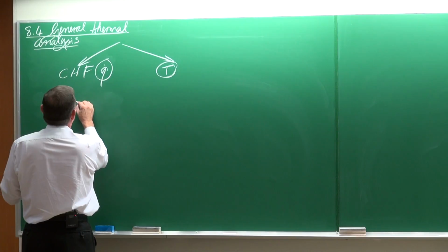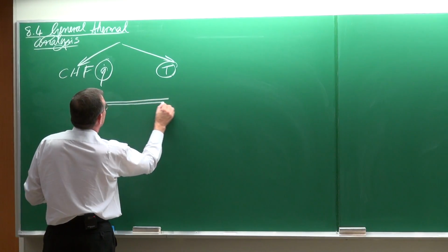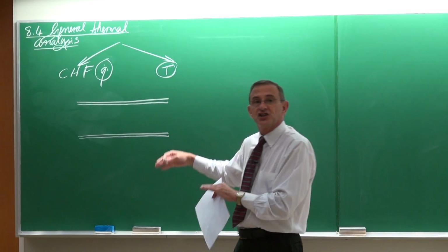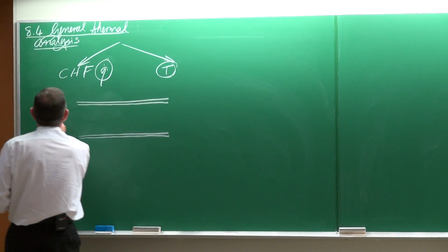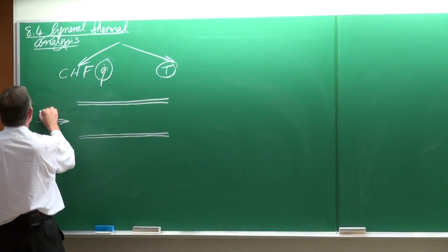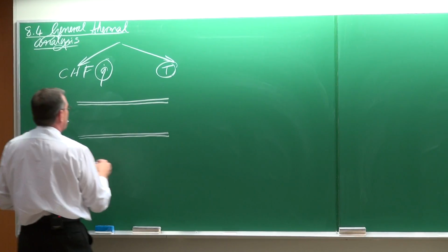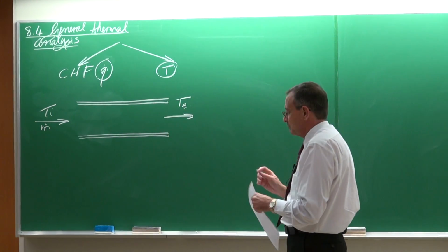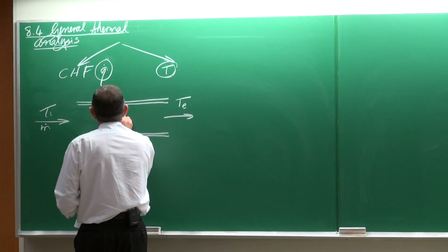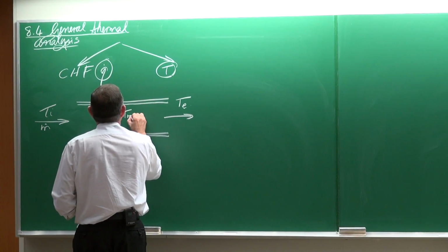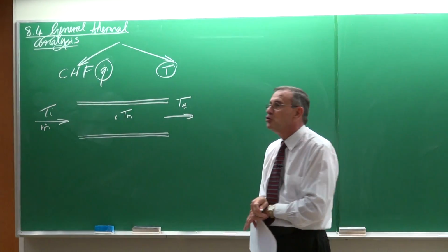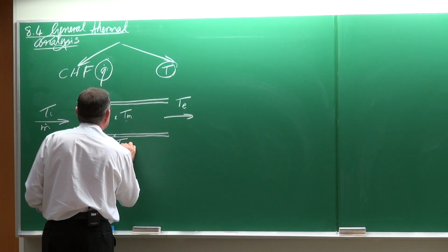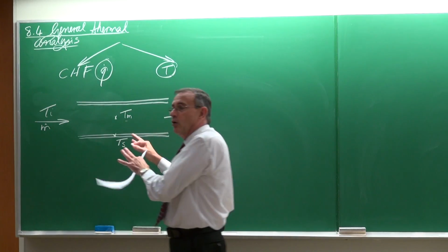The one thing that both of them have in common is that it is about flow through something, an internal geometry. And just to make it easy, we identify it as if it's like a tube with an inlet temperature there, Ti, and a mass flow rate m dot, and here is the outlet temperature Te, T for exit, outlet temperature. With all these problems, we normally have a temperature which is an average temperature for the fluid, Tm for mean, and then we've got a surface temperature, Ts. That is now on a micro scale.